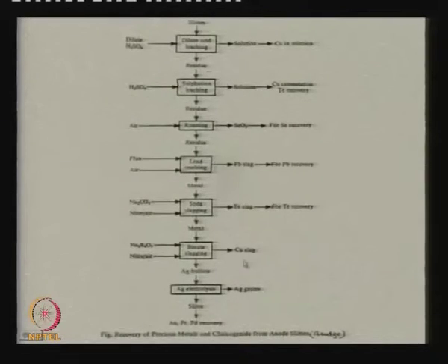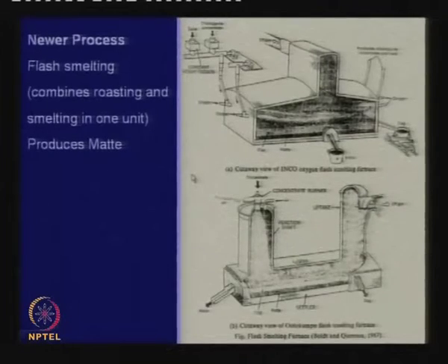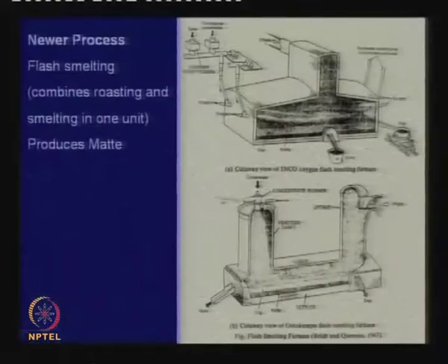We get silver, we get tellurium recovery, we can get lead, we can get selenium. These are all very standard steps that have evolved over centuries of trial and error. Of greater interest in copper metallurgy is how we are combining reverberatory, smelting, converting, and before that roasting all in one in continuous copper making processes.